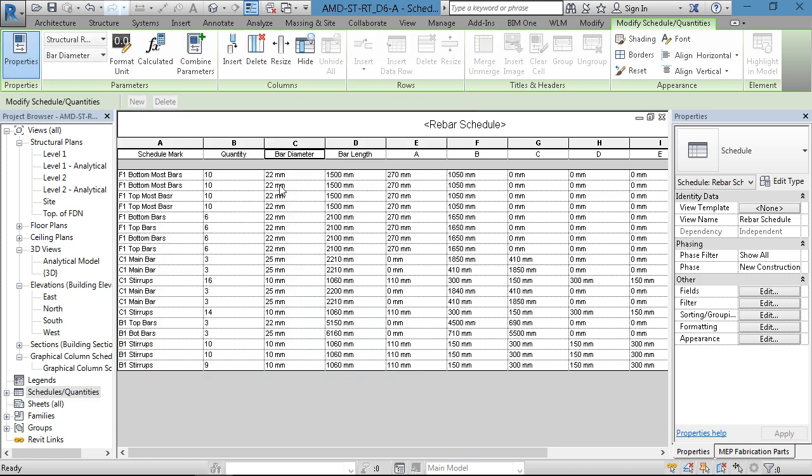Okay. So you got your schedule. Schedule, right click, schedule quantity, structural rebar. So you need that and this.